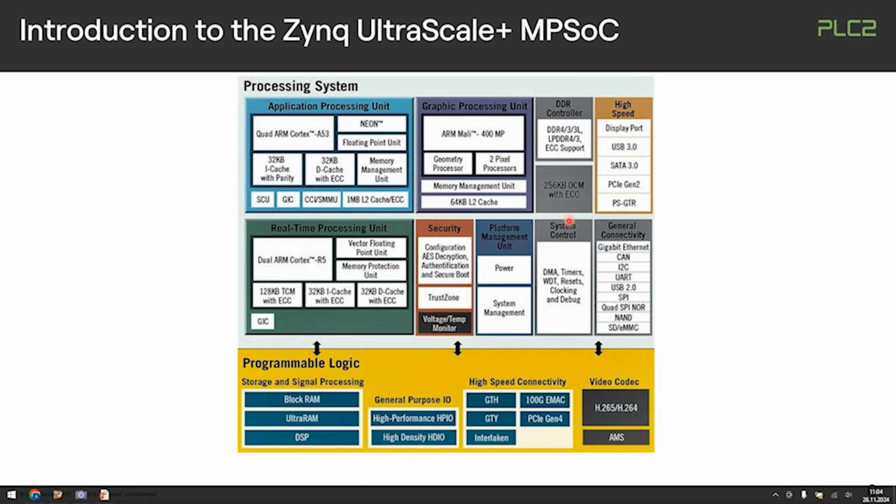And we're having lots of additional support. One main interesting thing is that you see that there's, of course, on-chip memory, but also the DDR external interface is governed by the PS system. So in the PL part, you would typically see all the things and elements that you know of the Xilinx FPGAs of old. You have the IO groups, and you have the block RAMs, ultra RAMs, distributed RAMs within the actual fabric, and the DSP blocks that go with the actual logic level that you want to see.